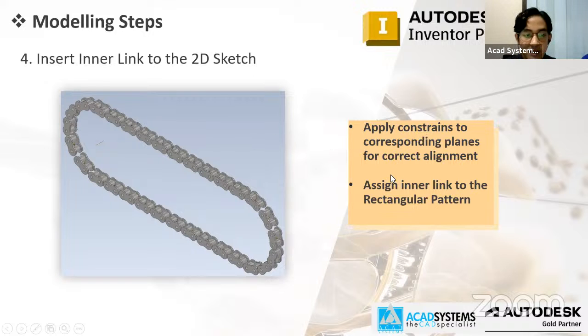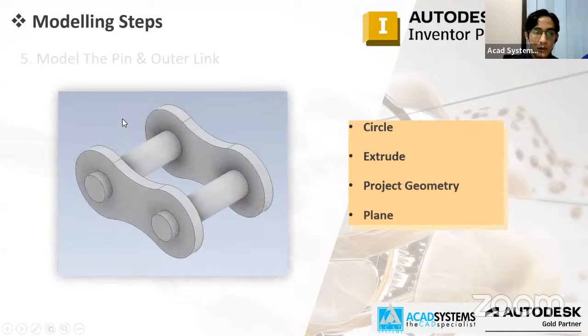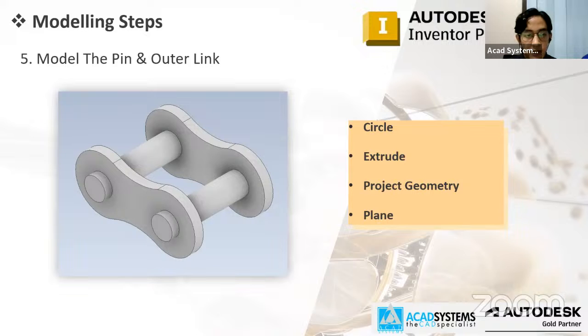Okay, and then we want to assign the inner link to rectangular pattern. Okay, which means we insert one of the link and then we use rectangular pattern for the rest. Okay, and then we will model the pin and outer link, same step as the inner link before.